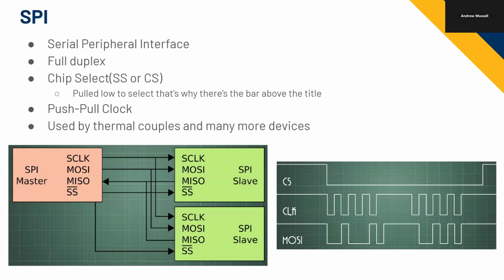So that's sort of a trade-off between I2C and SPI, right? With I2C, we don't need to use hardware resources, we don't need to route more lines, but we're using more bit resources because it's going to take longer to transmit. With SPI, you can route as many chip selects as you want, but you might run out of GPIOs on your master controller. So there's more hardware resources. It'll take up more space on your PCB, but then you have more data space.